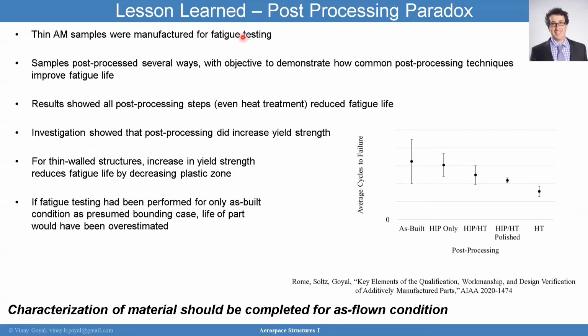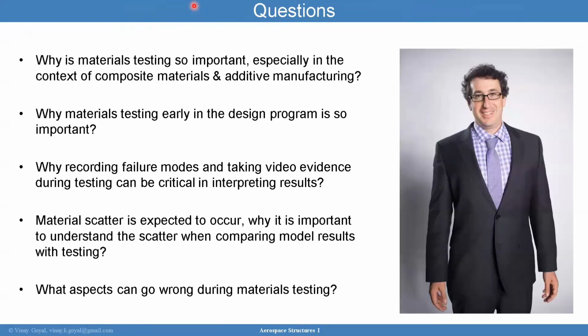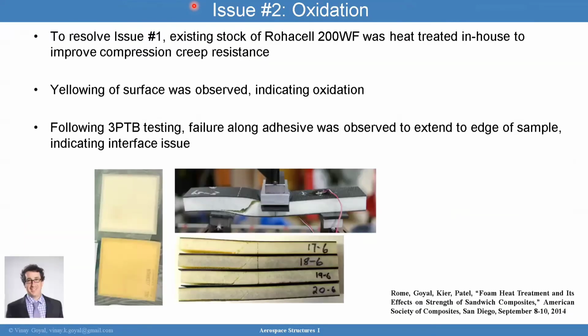Yeah, I think if you go back to one of the early slides with a 3-point bend, right there. I think at some point we added those little rubber feet there, and we made that wider because we didn't look at it initially. I think we had rollers there, and we were getting local failures, and so we went and did higher fidelity analysis and said, aha, we need to widen this. Now, that wasn't a problem with the test per se. That was a problem with our design of the test.